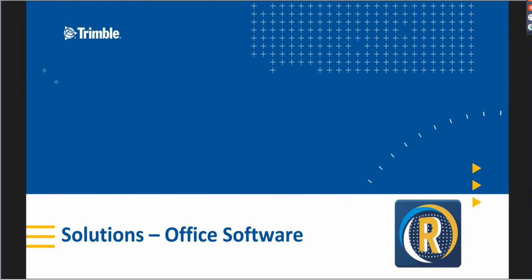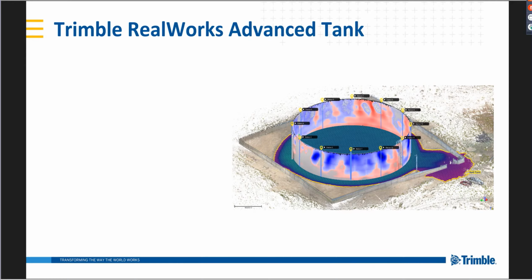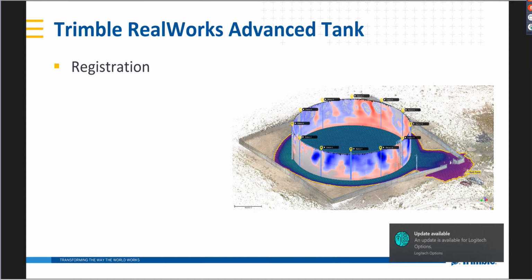I just described. And then there's creating deliverables and getting information and meaning out of your scan data. And that's all done in the Office software. The Office software that we use is Trimble RealWorks Advanced Tank. Now, this is a software that's used specifically for laser scanning, and this edition is made specific for those in the storage tank industry. It handles all of the registration, putting each of those scans together for you, whether you're using targets or no targets, so you have flexibility to work however you like.